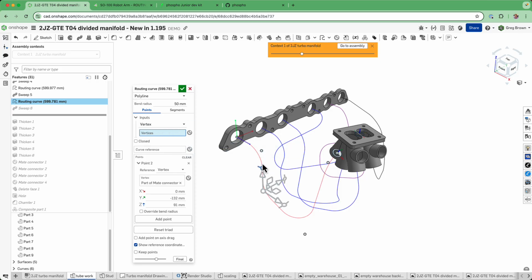There are other ways of getting vertices in other than just digitizing them like we did. You can actually import CSV files, right? So CSV data of the X, Y, and Z locations for a series of points, you add that to your document and then just import them, and then it will run the curve through them. All of the other same things apply.